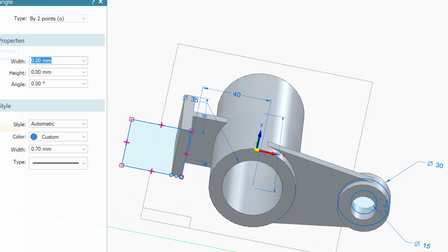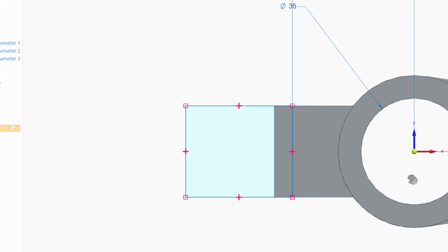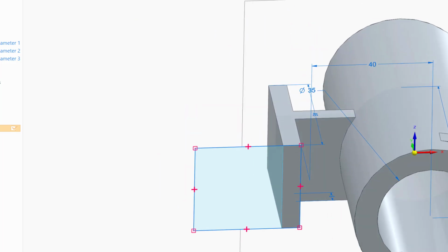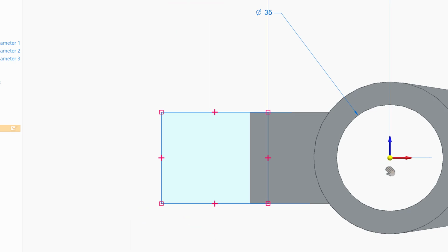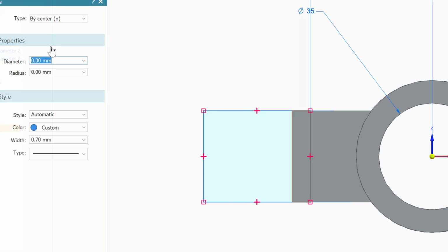Go to the front plane. I don't want to bother because really everything is locked already. So anything is going to be drawn where? Parallel to this plane here. Okay, on the same plane here. So let me go to Solid Edge, front plane. Get circle by center, and this will be 30, and come exactly in the middle of the line here.